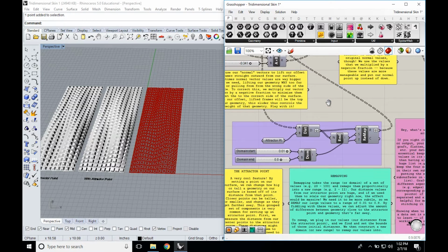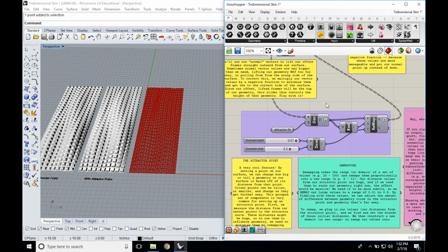Grafting and flattening and all of this can be really confusing, and sometimes if a script isn't working, the best thing to do is just to try and graft it or try and flatten it, and you might get what you need. I've started to understand it much more after using Grasshopper for a while, but still sometimes I just experiment and it works, and that's exactly what I needed to do. So when in doubt, maybe just try it out.